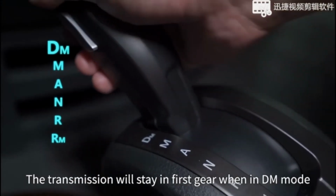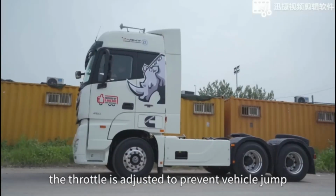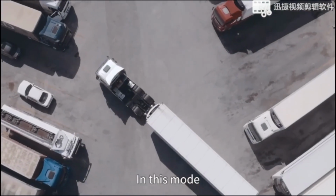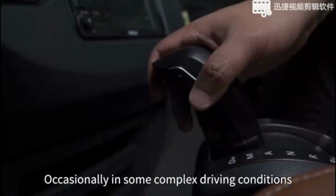The transmission will stay in first gear when in DM mode. In this situation, the throttle is adjusted to prevent vehicle jump. DM is very precise for moving in small spaces, parking, and so on. In this mode, the vehicle more accurately adheres to the driver's needs.